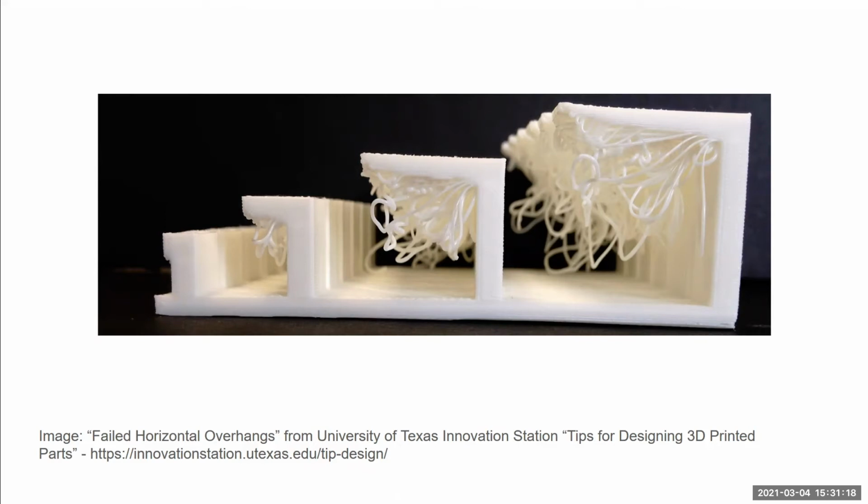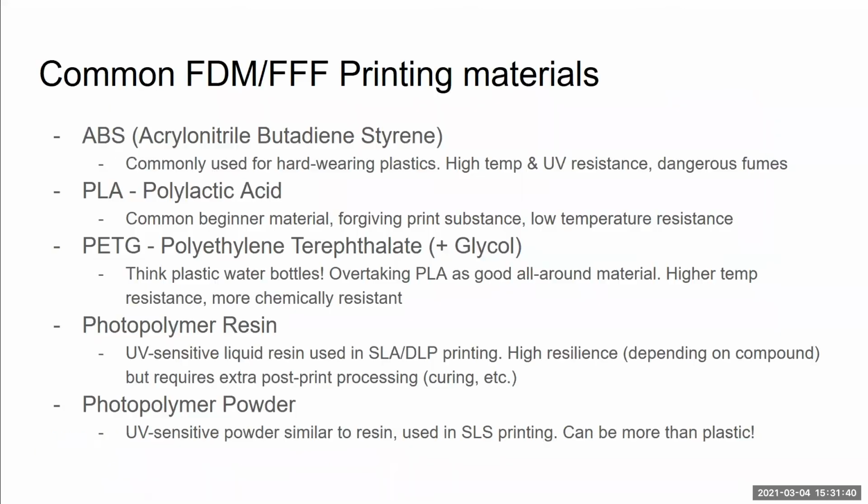But also, that's why you have things like supports that we saw from the traffic cone example, something to at least give the bottom of the print a support. The support is a plane for that printer to touch onto to create a nice solid bond.